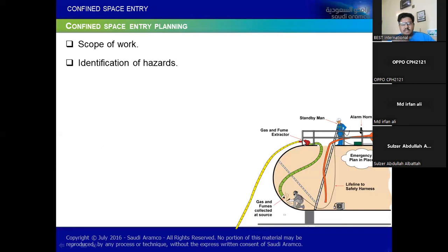And imagine with this confined space, if some liquid was there, some pipelines were attached, and the client says that you are the one going to isolate, you are the one going to put locks and tags, do you need another permit before starting, or you believe two are enough? Before this, we have to close this confined space. We require isolation first. Then after that we have to apply for confined space and hot work.